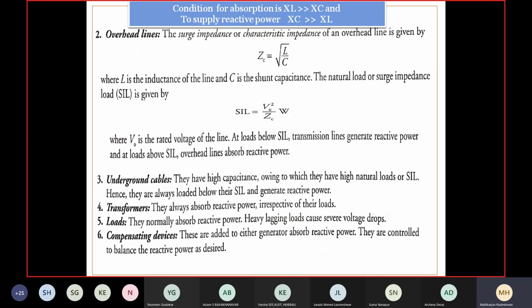Then who has to supply this reactive power? It becomes a burden on the generating system. If I do not have any compensating mechanisms initially, the reactive power has to be delivered by a source, the source being the synchronous generator. But the synchronous generator has a limited scope to generate it, because that is not the significant role of generation. They are meant for active power generation. So this causes a bottleneck issue in the operation, because there is an indirect demand of reactive power by the overhead line, being more inductive in its operation.